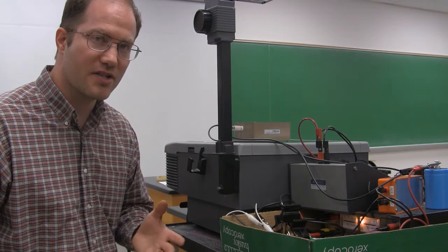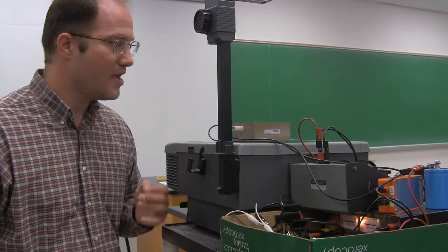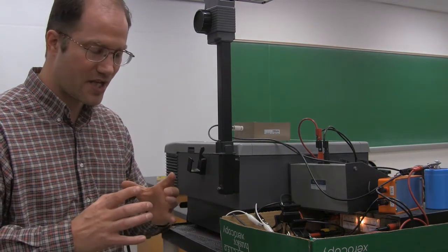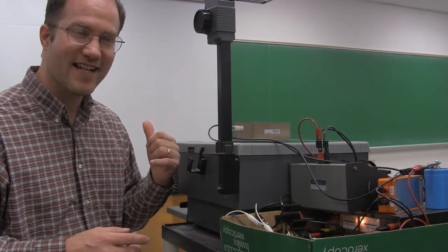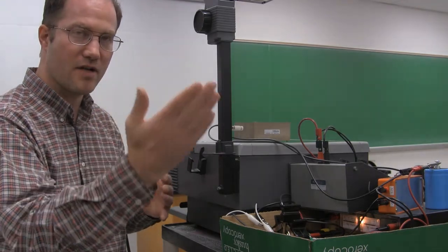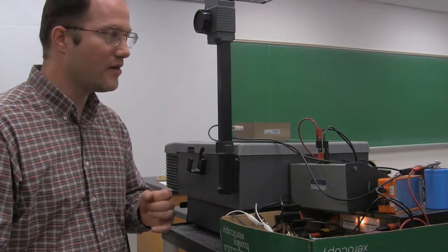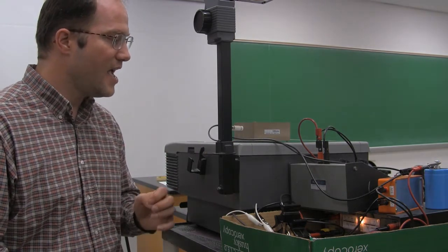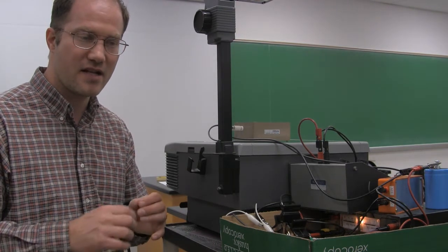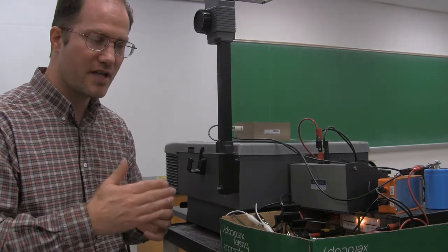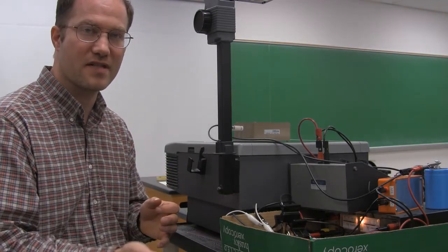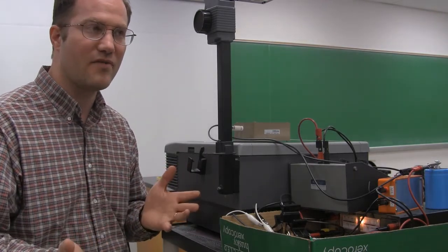Now, to measure the charge and discharge curve of the capacitor, you are going to watch a projection on a screen behind me. And as it charges, that needle will go from 0 all the way up to 100. Okay, 100 volts, I guess we could say. And so as it does that, we're using a split timer. You can see, starting at time equals 0, you can get time at 10 volts, 20 volts, 30 volts, 40 volts, 50 volts, 60 volts, all the way up to maybe 90 volts.